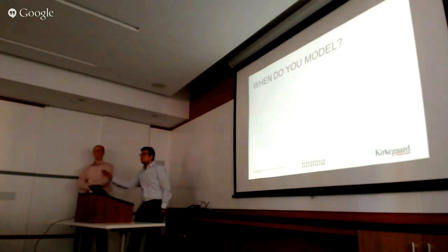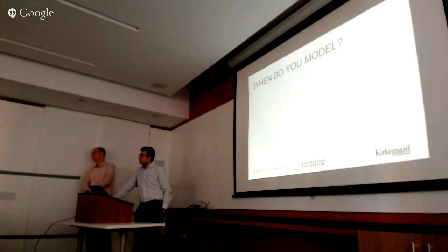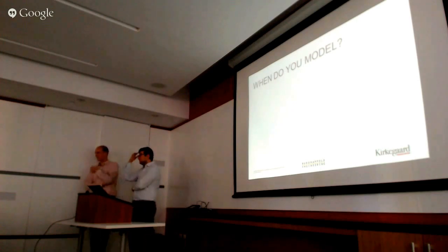So you always model? I think it depends. Yes. Both on the complexity of the problem and on the sensitivity or critical nature of the use for that space. So, if there's a utility closet, there's no need to model the sound there, because you just do a rough calculation and ensure that it meets whatever standard. And that's generally good enough. If it's a critical listening room or auditorium,